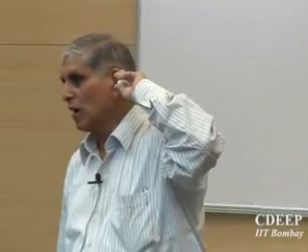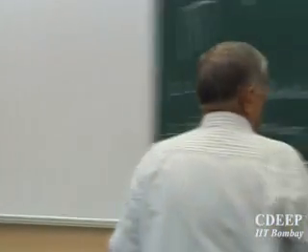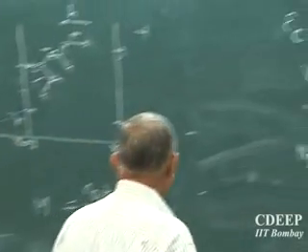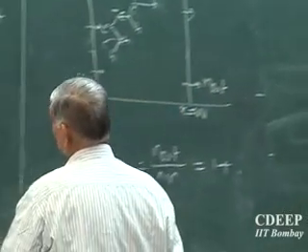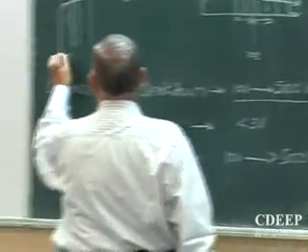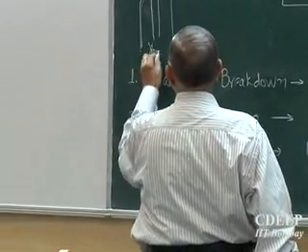The punch through device, with the base length so adjusted that it breaks down at the value of your choice. Most of the circuits which use breakdown values known to them a priori use a punch through device.